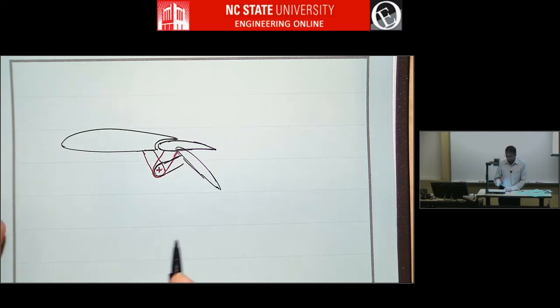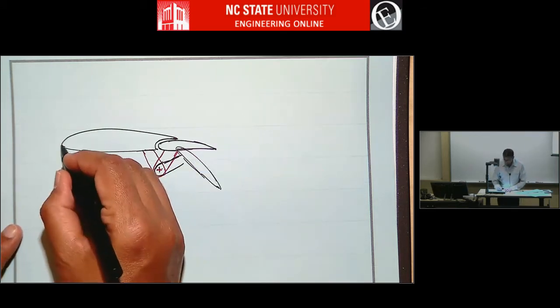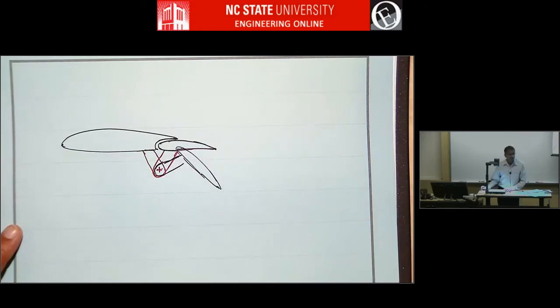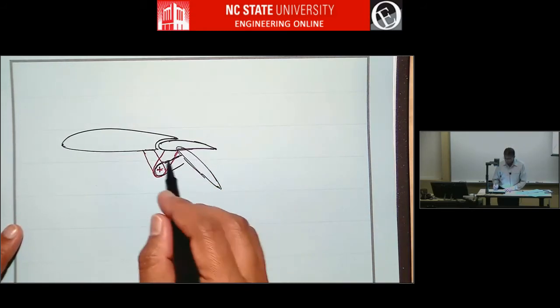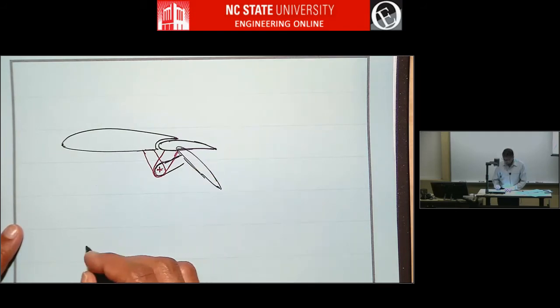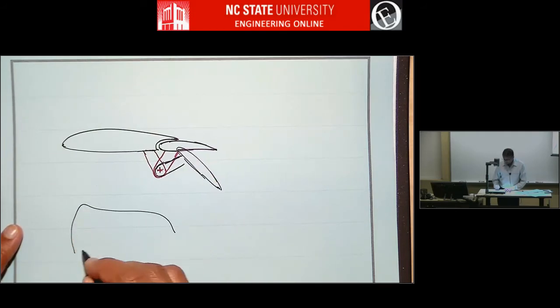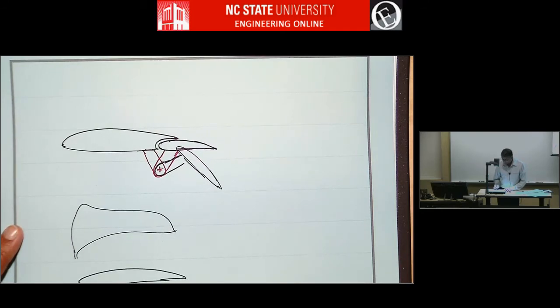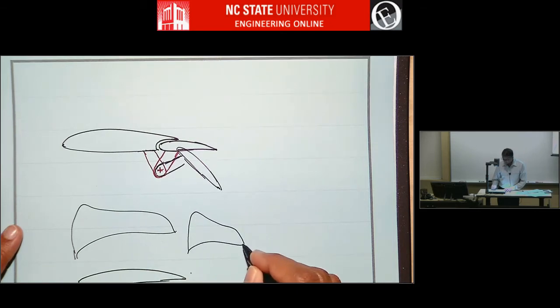Usually the chord is defined as what is for the original airfoil. So even though you might have a pressure distribution on the deflected airfoil that looks like this. This is the main airfoil, and then the flap is, let's say, like this, and so this flap deflection will be, flap pressure distribution will be something like this, right? I'm just sketching something. But the actual chord is this.